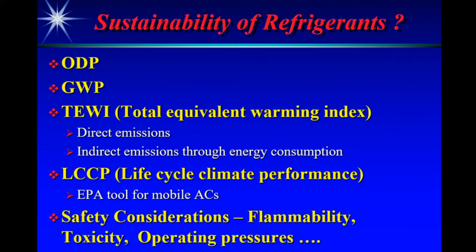The second aspect is the global warming potential. This has picked up quite a bit in the last 2 decades, and emphasis has shifted to now GWP. So HFCs, which were conventionally thought to be very good, many of them have very high GWP, particularly refrigerants like HFC 134A.